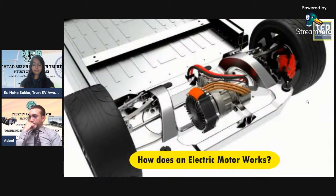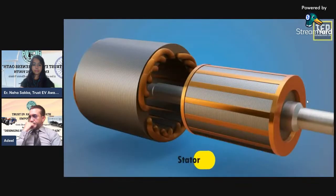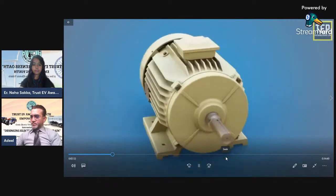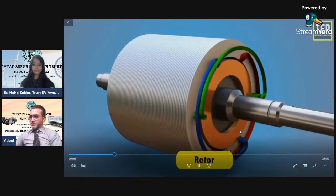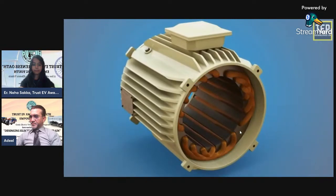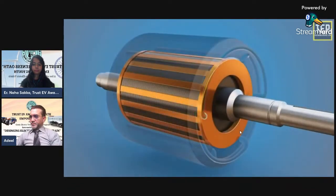If you want to understand how an electric vehicle works, you need to be familiar with the physical elements of the electric motor. And it starts with understanding the principles of its two major parts, the stator and the rotor. An electric car motor works using a physical process. This consists of using a current to create a magnetic field at the fixed part of the machine, called the stator, whose displacement sets a rotating part, called the rotor. The difference between the two is easy to remember. The stator is static, while the rotor rotates. In a motor, the stator uses energy to create a magnetic field that then turns the rotor.